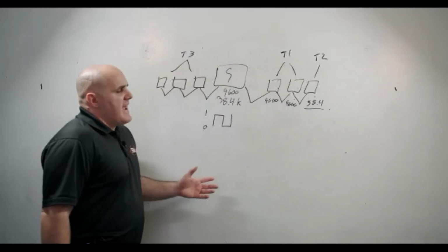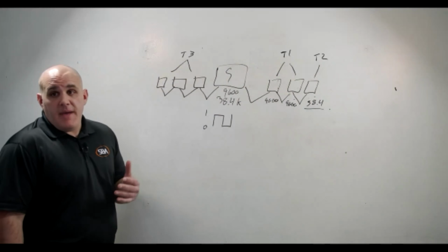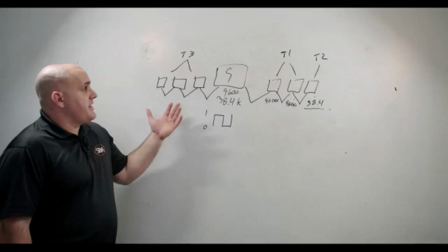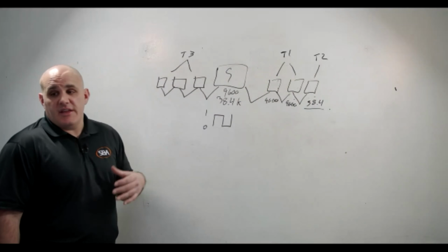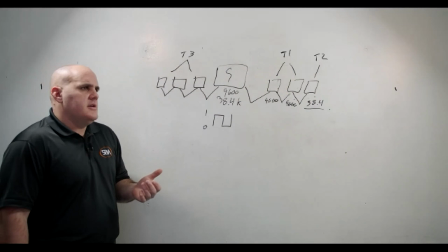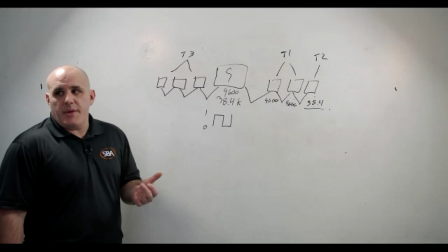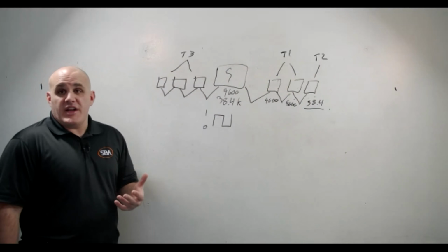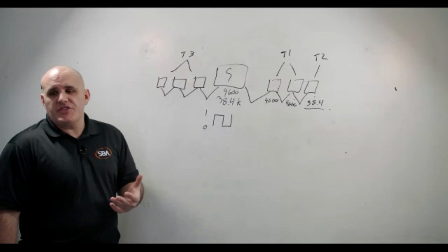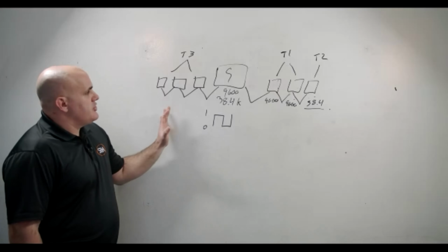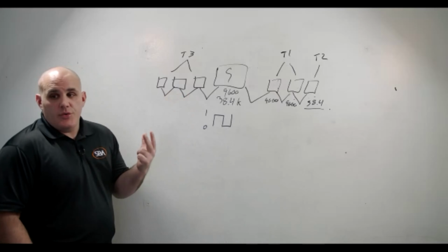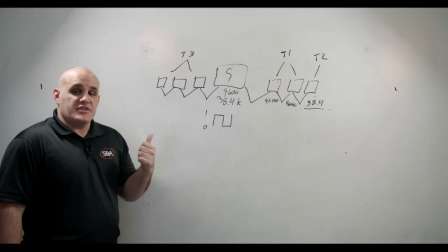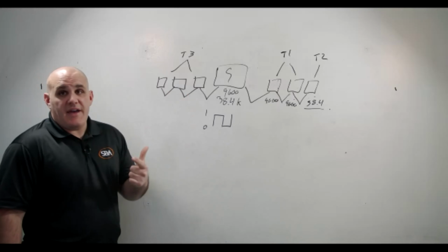So a MAC address issue. MAC addresses are how we physically address our BACnet devices. They're an 8-bit array that enables you to address from 1 to 256, if I remember correctly. And MAC addressing is going to enable us to set the physical address of our device. But BACnet exists with two address types. You have your MAC address and you have your device ID, both of which need to be unique.